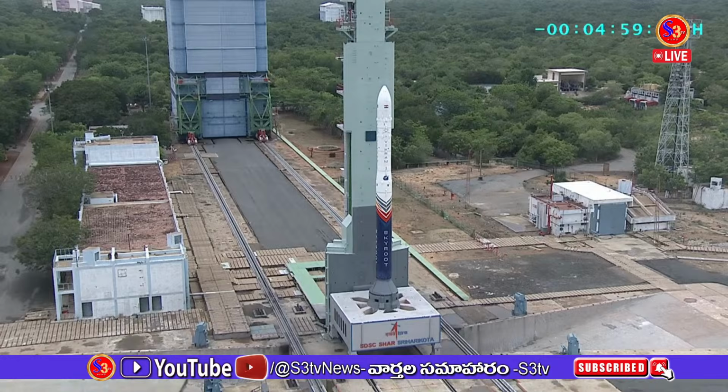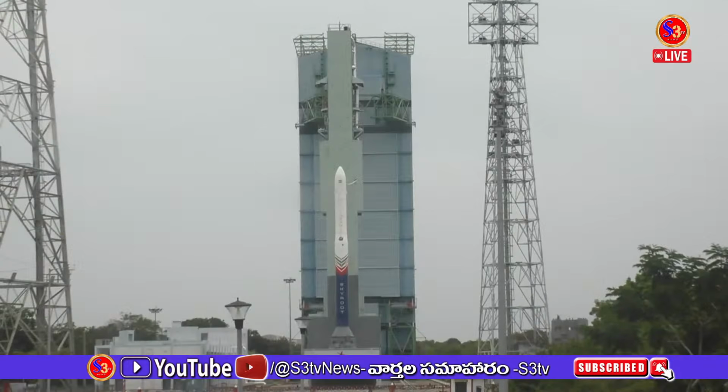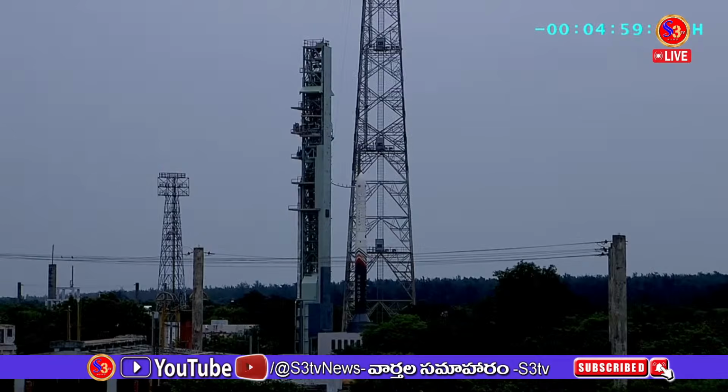So when we are dealing with rockets, there is no outside air that can enter and be utilized for propulsion. So we have to carry our own bottles of oxidizers and fuel. And once the rocket is ignited and it's on its way through the entire flight, the propellant is expelled. And when the stage gets burned out, it's also thrown away or jettisoned. So that is why the rocket keeps accelerating, because there is less and less mass to push.